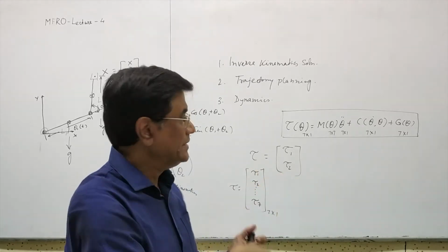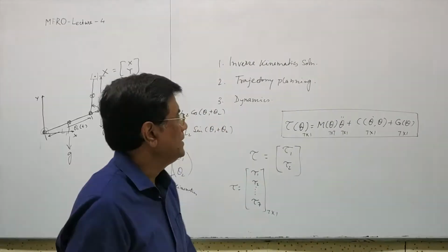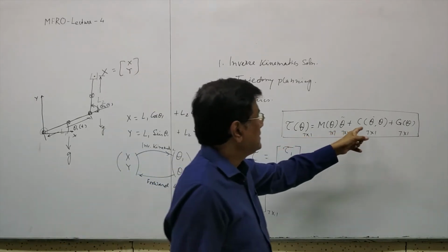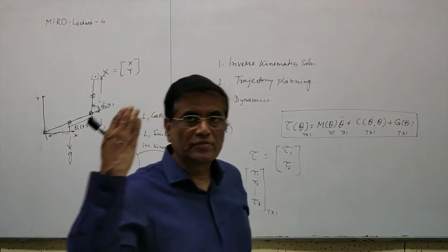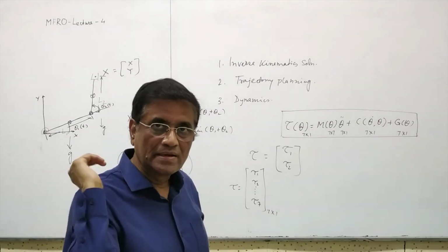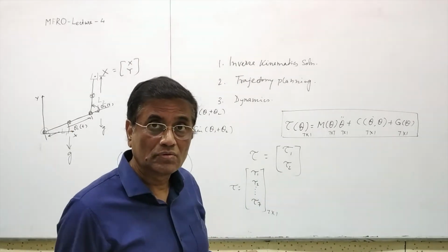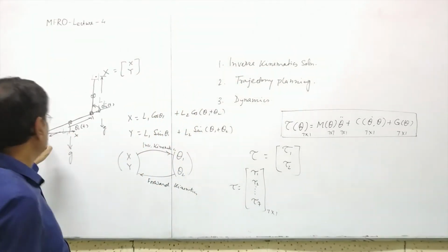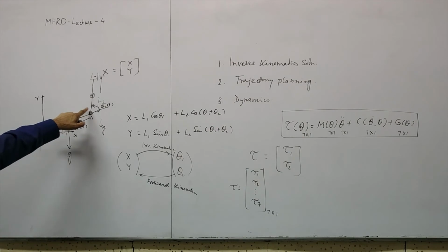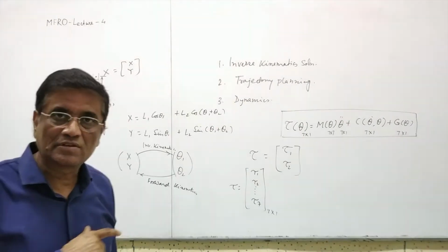Okay, I will derive this completely, from the fundamentals. So you will see that it will also have centrifugal force, because now my hand is undergoing some rectilinear motion together with curvilinear motion also, right? Because this is a revolute joint type of robot. It's not a prismatic joint.